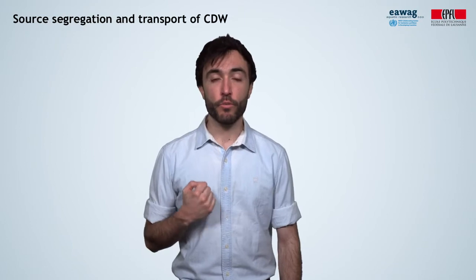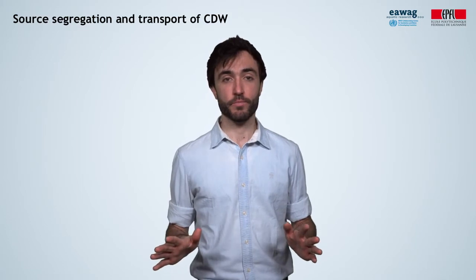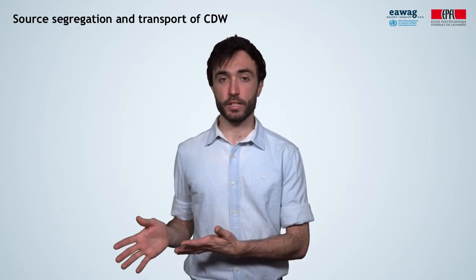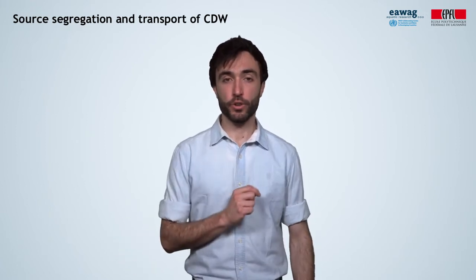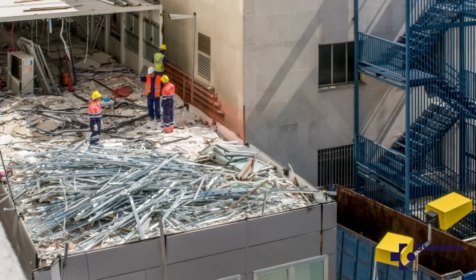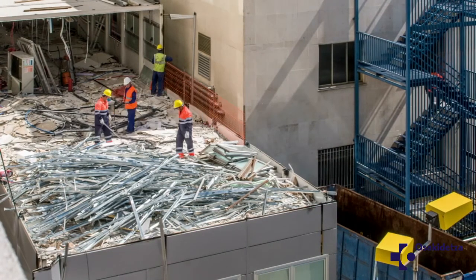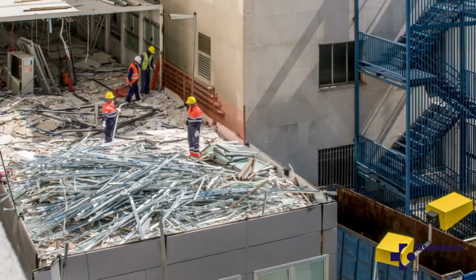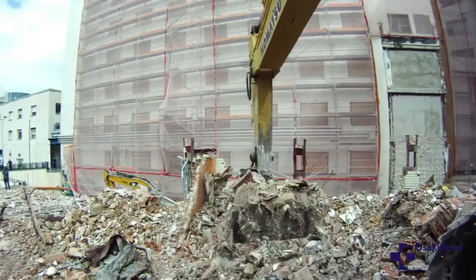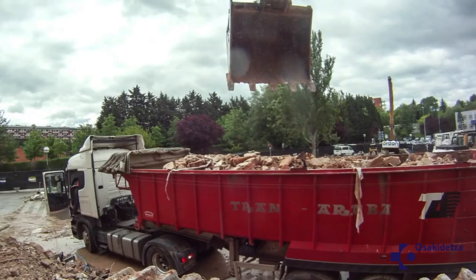Due to the variety of waste materials, it is important to segregate construction and demolition waste. This can be done at source, ideally, or in specialized treatment plants. This way, each waste stream will be managed as required. Here, we see how these operators have separated out all the metallic frames of this soon-to-be demolished building. Then, the materials need to be transported to, ideally, a processing plant for further reuse or a final disposal site.